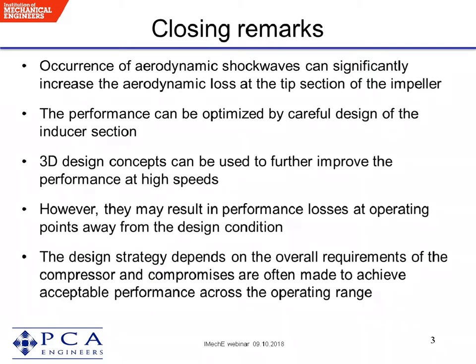Yes. As far as the single-stage compressors are concerned, I mentioned that in the presentation that a compromise has to be achieved. So if you're in a car turbocharger, if you're concerned with low speed, low flow, that really implies that you are looking at smaller trims and smaller throat areas.